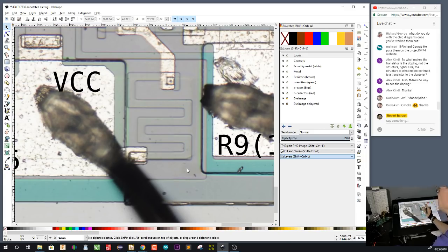There were no resistors to be found anywhere. So basically, you would see this square over here and nothing over here. You would just see these two bits of metal, and they just appeared to end. And I was like, well, there's got to be a resistor in there. I just can't see it. And I discovered that with hydrofluoric acid, the p-doped material actually got stained, so I could see the resistors.